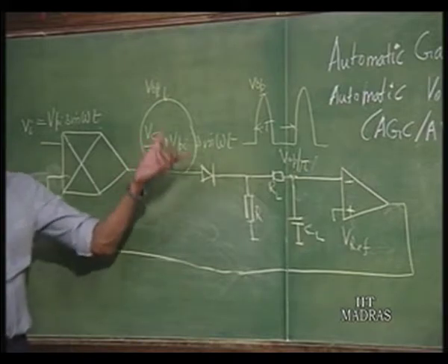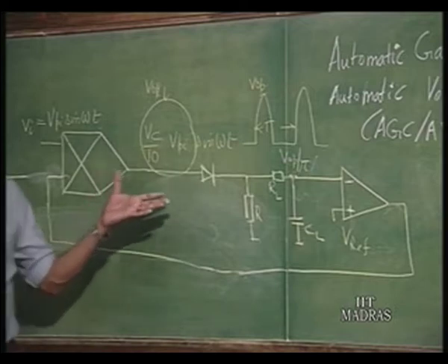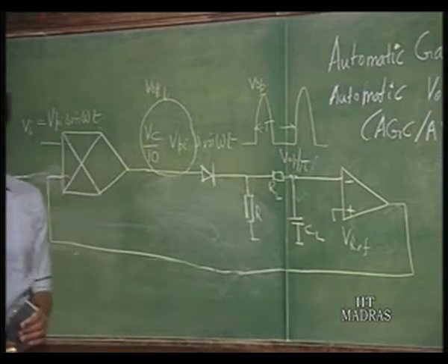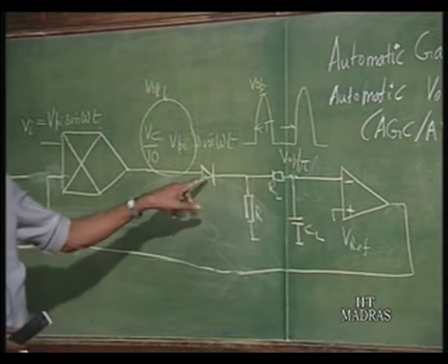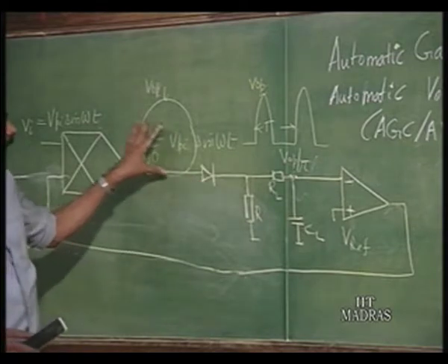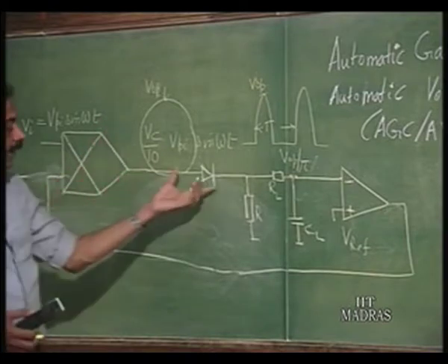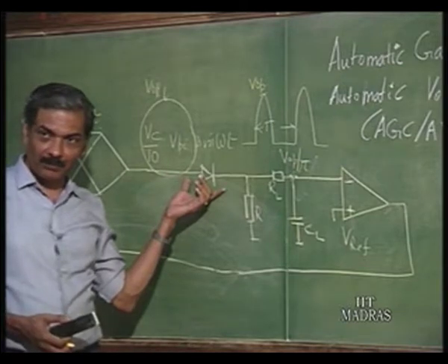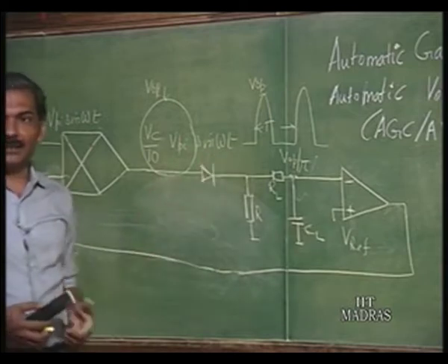So, basis of such automatic gain control and automatic volume control, okay, the rectifier filter combination is one part that is necessary there. Normally, if the voltage that is inputted to such a system in the communication area is very small, then V gamma of this diode will hinder this rectification properly. Right. So, for that purpose we can use what is called a precision rectifier here.